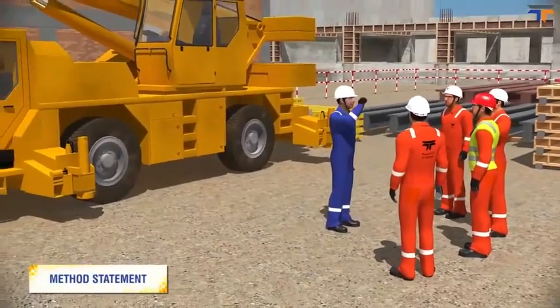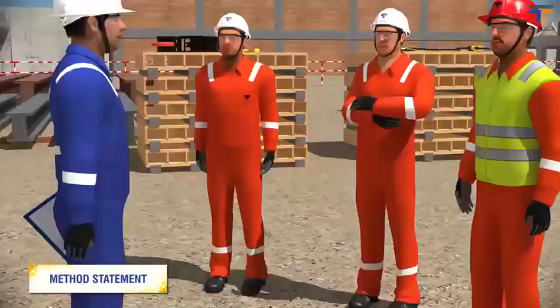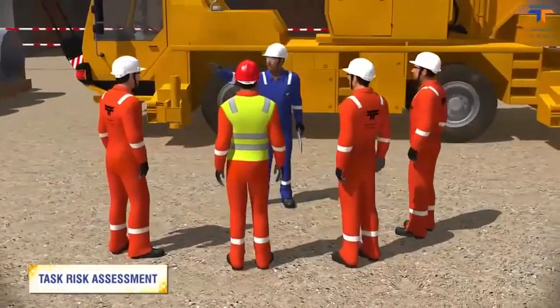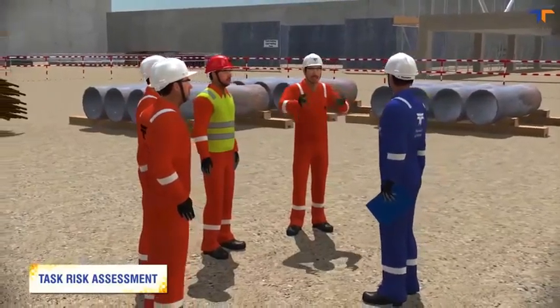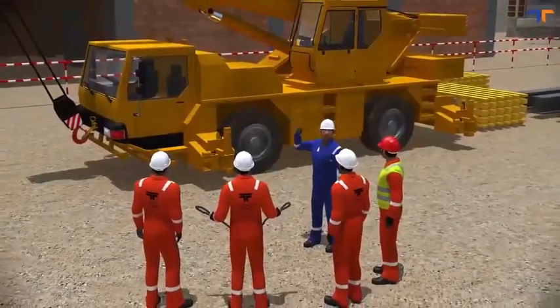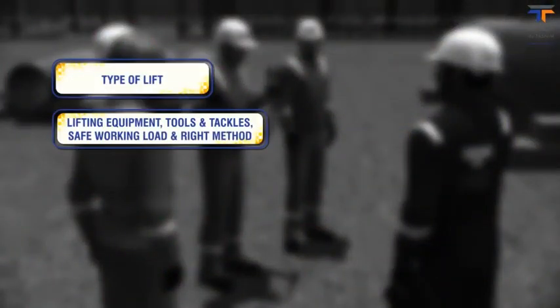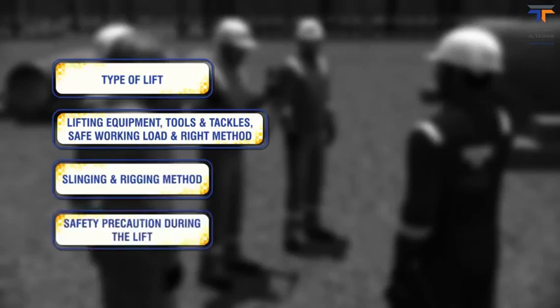Method statement. Method statement is a detailed statement of work, which includes scope of the task or activities, hazards involved in that task, and the safe work methodology of the task. Task risk assessment. Discussion on the site-specific or lift-specific risk assessment and control measures, and if there is any change in plan or process, dynamic risk assessment to be carried out before starting the job. Lifting plan. Lifting plan contains the essential information for the particular lifting operation, such as type of lift, selection of lifting equipment, tools and tackles, safe working load, and right method to use them. Slinging and rigging method. Safety precaution during the lift.